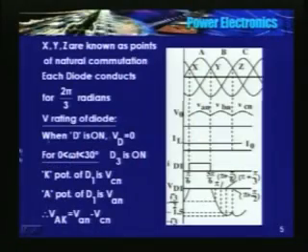Okay, the magnitude is same as that of the load current. So phase A supplies power from pi by 6 radians to 5 pi by 6, and it is 0 otherwise. So if I find the average value of this, it is finite. So source supplies a DC component of current to the load. The effect I have already discussed in the single phase.